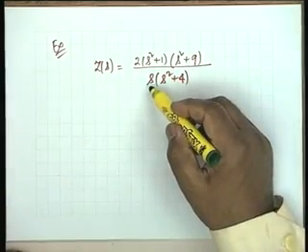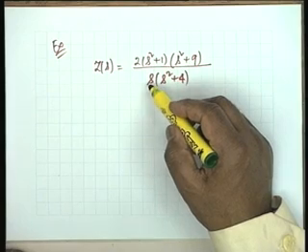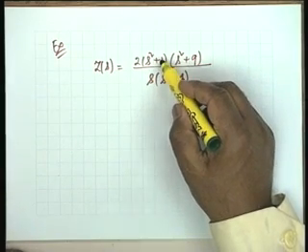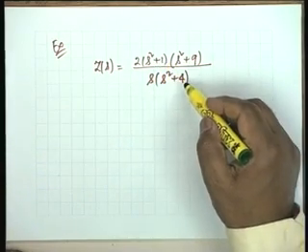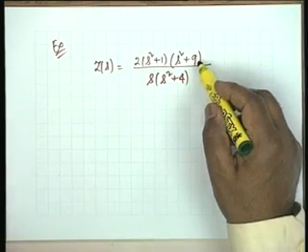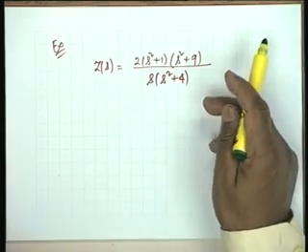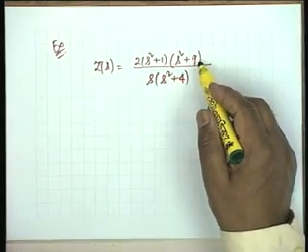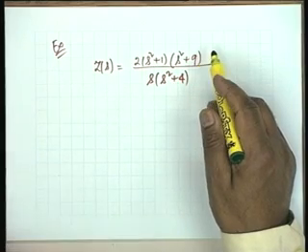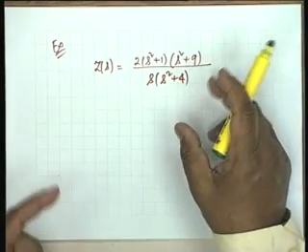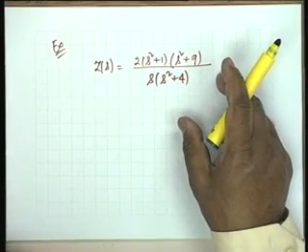You see, the first critical frequency is a pole at the origin, then a zero at root 1, then a pole at root 4, which is 2, then a zero at root 9. So the poles and zeros alternate. It is a purely odd rational function. Okay? There is nothing in this function which can disqualify it for LC. Therefore, it is an LC function.